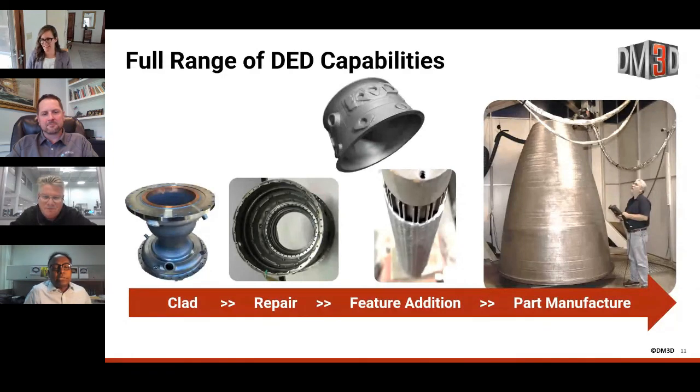Well, Giles, I just want to add one thing here. In a DED, you could stop the process in between and bring in the scanning instruments and measure the part intermittently. You can. Not every layer, but certainly intermittently. That's absolutely true. And on large scale, you could do that at any time, couldn't you? And you could use the same technique as you use for final inspection. If you've got something that's taking 2 weeks to run, that's probably a pretty sensible thing to do occasionally.